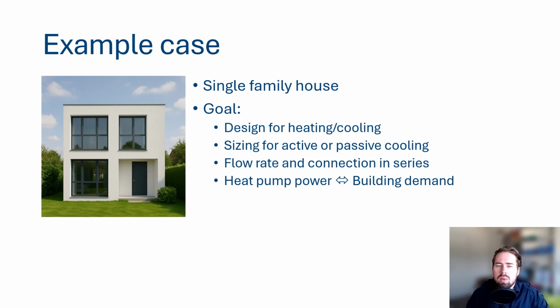So this is the example building we have. It's a single family house and the goal of this exercise is to learn what the difference is when you design for heating versus design for cooling. So typically, historically, ground source heat pump bore fields were designed to cope with the heating demand of the building, and cooling was more nice to have. But in more prestige buildings, in hotter areas, more affected by climate change, cooling is not so much a nice to have, but more a design constraint. So this needs another design methodology, needs another bore field design. So that we will focus on in this video.